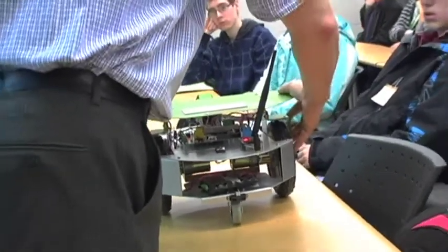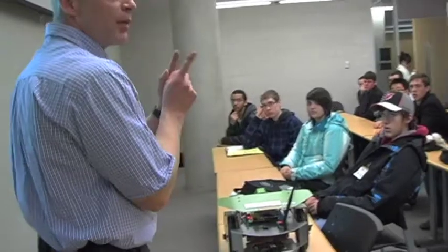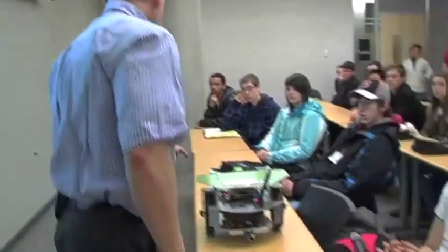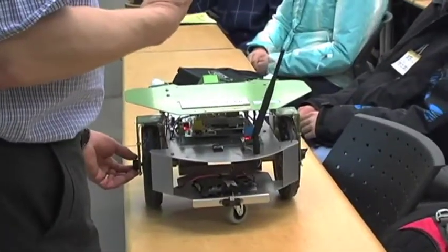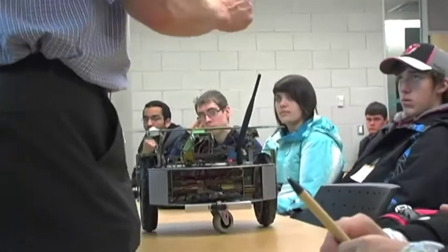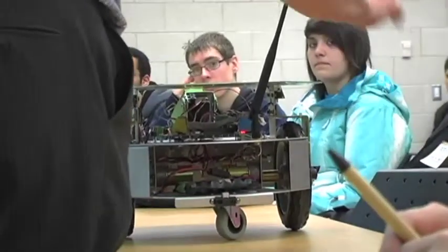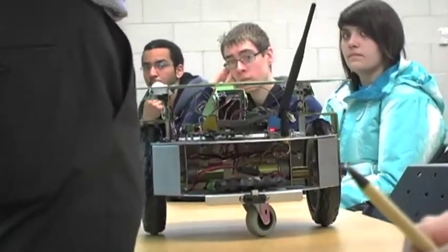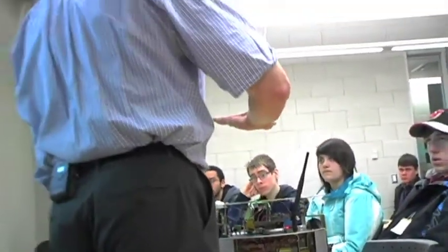That's not perfect, because now the problem is, I put some power to this motor. How much power should I put to the other motor? The motors will not be 100% the same. So the idea is, I'm putting power to one motor to make one wheel rotate at the desired speed, and then I'm taking the other motor and trying to match the speed. Since I measure the speed on the one encoder, I can measure the speed here. If I'm a little bit too fast, I slow it down. If I'm a little bit too slow, I start speeding it up. That's how I get this thing to move on a straight line.